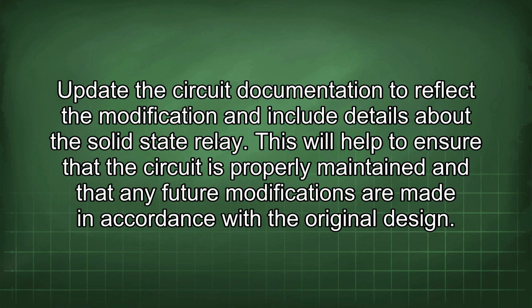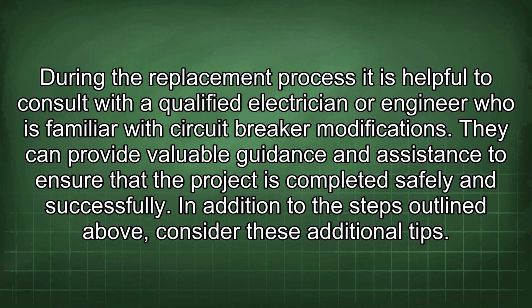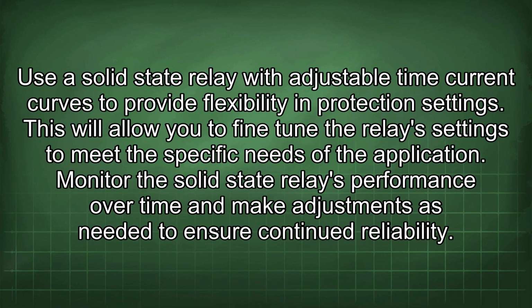with the original design. During the replacement process, it is helpful to consult with a qualified electrician or engineer who is familiar with circuit breaker modifications. They can provide valuable guidance and assistance to ensure that the project is completed safely and successfully. In addition to the steps outlined above, consider these additional tips. Use a solid-state relay with adjustable time current curves to provide flexibility in protection settings. This will allow you to fine-tune the relay's settings to meet the specific needs of the application.